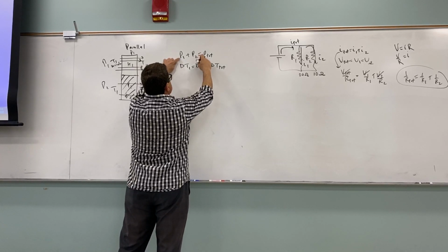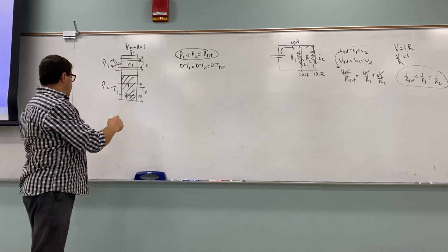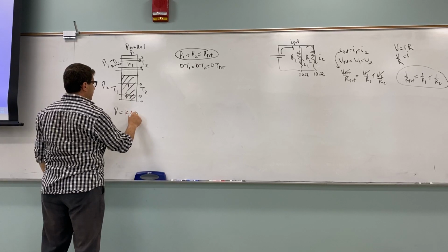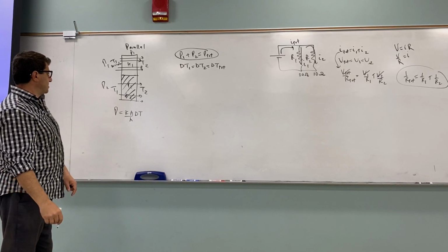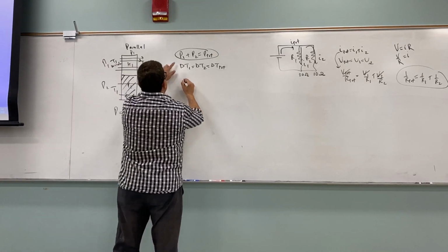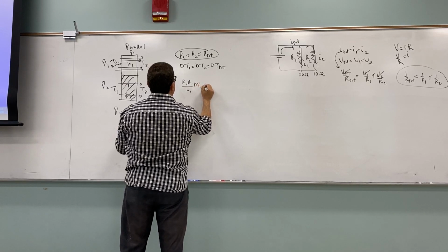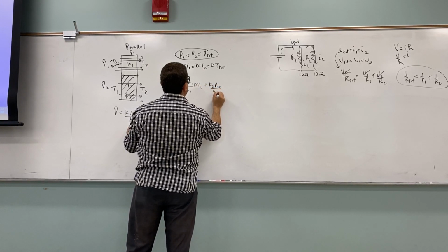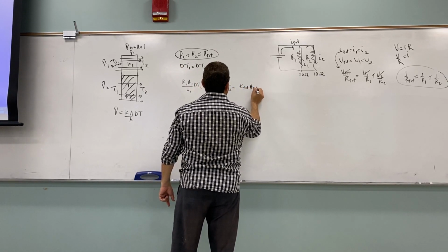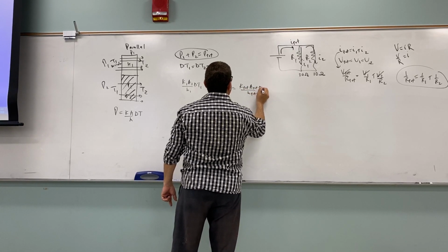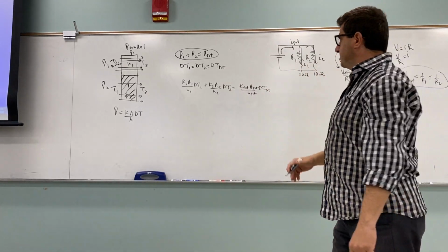So now look at the one that adds up and then use the equation that connects that to the rest, right? So which is what? Our famous equation, K A delta T over H. So I'll replace delta X by H. So then you're going to have here, P1 is going to be K1A1 over H1 delta T1 plus K2A2 over H2 delta T2 is equal to K total A total over H total delta T total. And then whatever is the same, you cancel that.